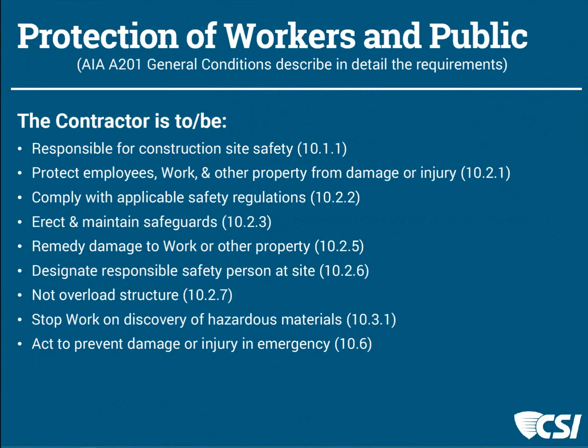As my mentor said, if you see someone who is in the path of danger, then you have no choice but to professionally act. So if they're deep in an excavation with no bracing or trench protection, tell them to get out of the ditch because they're in imminent danger. Now, that's drastic because we're involving ourselves in job site safety.